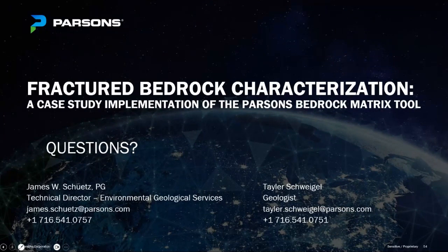I guess you can prioritize certain techniques. Like the fluid replacement testing is really inexpensive relative to some of the other tests. So if you can't do geophysics at the site, we can do fluid replacement. There's ways to layer things together to get to what you need within the budget that you have for your project. And you might not need every single tool at every single site, depending on how complex it is or what you already know about the site.